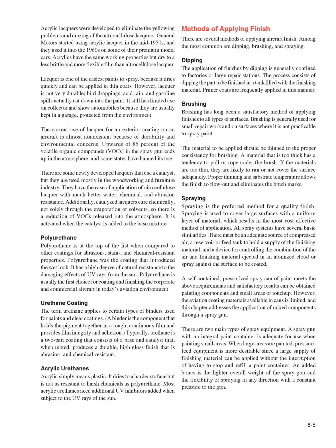Acrylic urethanes. Acrylic simply means plastic. It dries to a harder surface but is not as resistant to harsh chemicals as polyurethane. Most acrylic urethanes need additional UV inhibitors added when subject to the UV rays of the sun. Methods of applying finish. There are several methods of applying aircraft finish. Among the most common are dipping, brushing, and spraying.